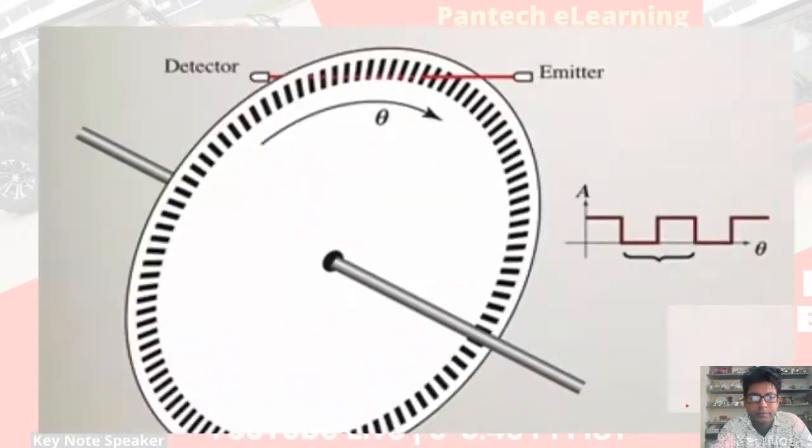Okay, now coming to the incremental encoder. In the incremental encoder it is much simpler. Here there are holes like this, and on one side the LED, on the other side the photodetector. Now if the disc rotates, you will get this type of waveform, a pulse train, on off on off on off. So basically you are mapping the rotation,